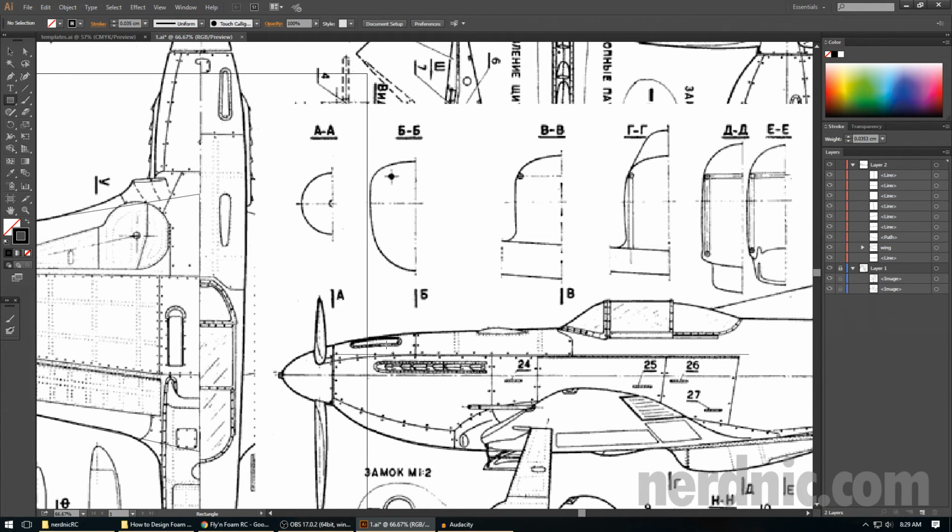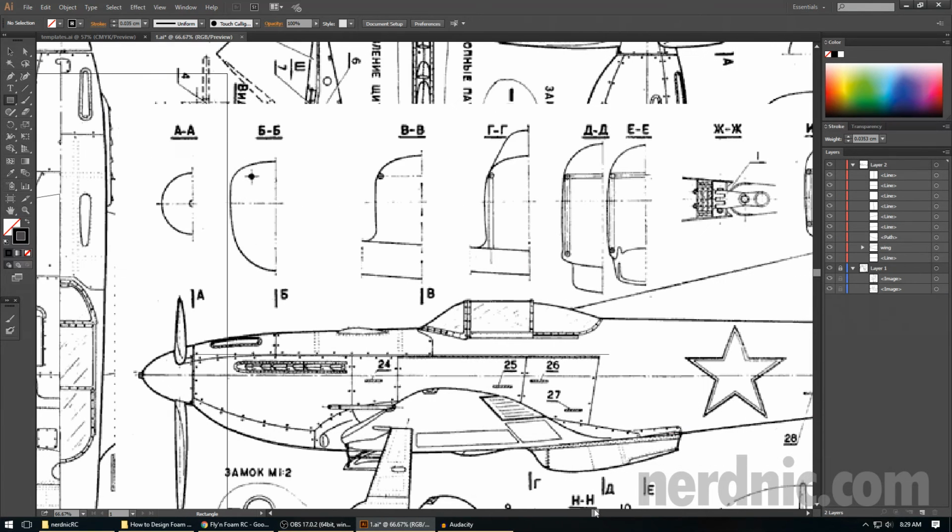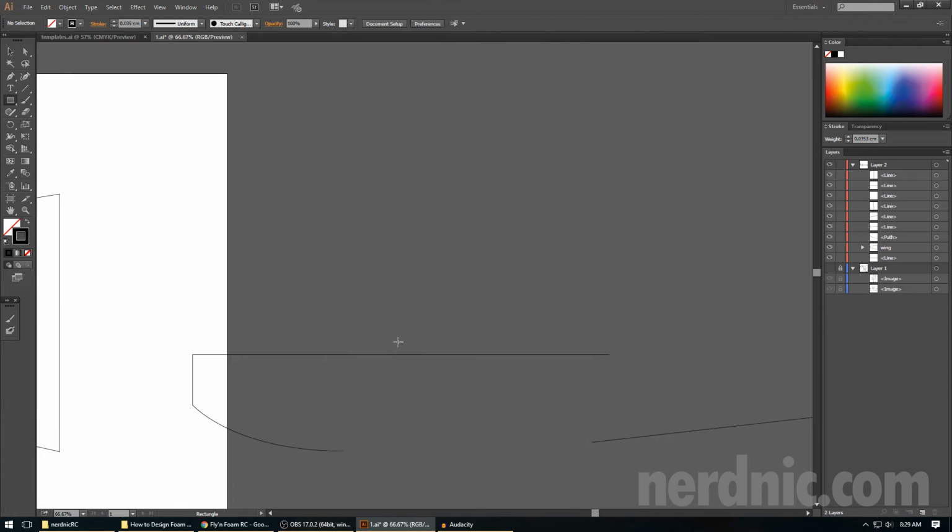Okay. Other thing, just to quickly make reference so you can look at your plane, because some planes are different, is I checked this former, right, and this line would have been fine. I got good curve. I'll just visually look at the next formers and see, do any of them have a crazy shape that would be impacted by this? Because if one of your shapes is really round and this line is too high to where you would lose that shape, then you need to drop it down for all of them.